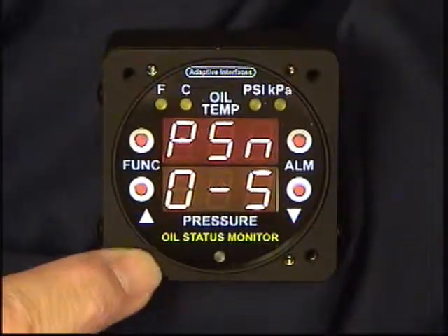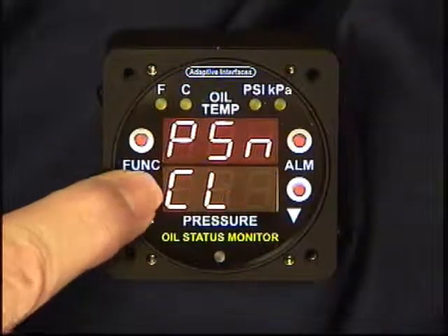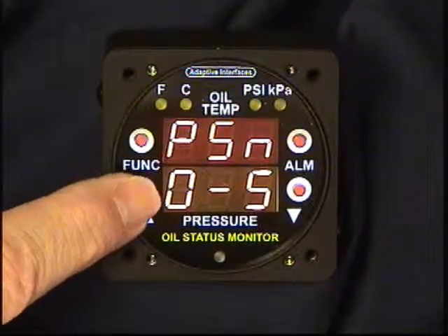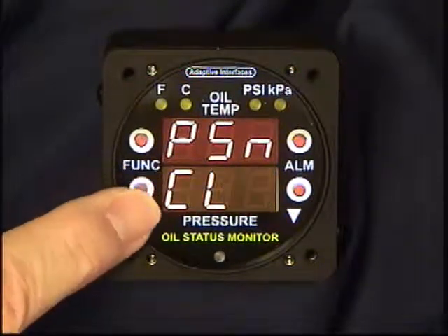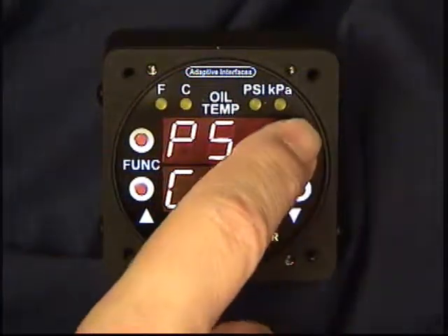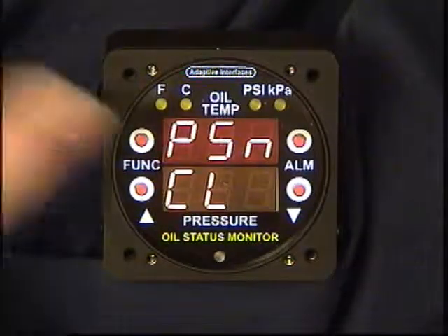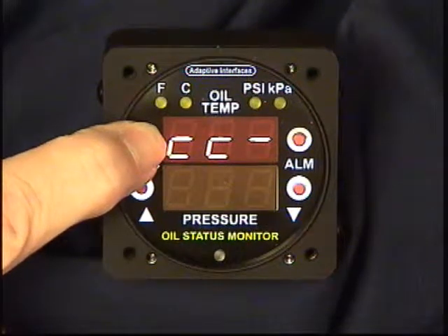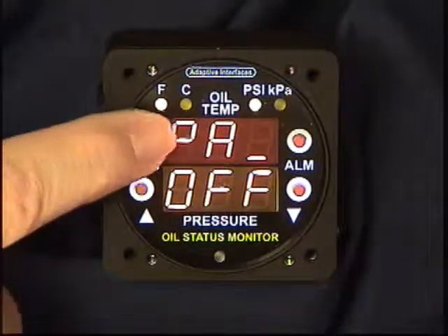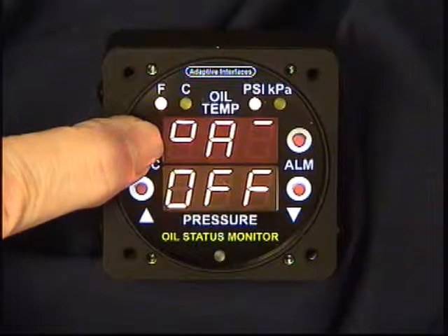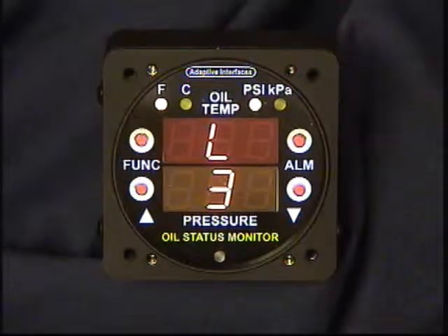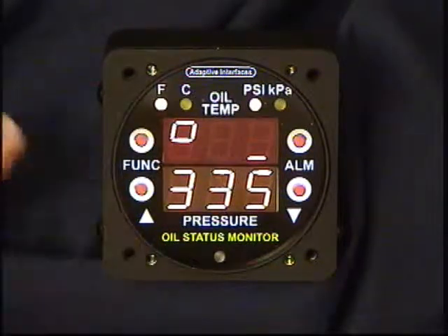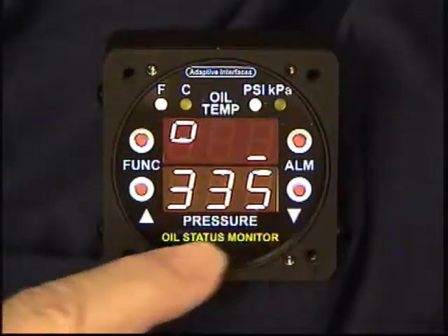And the pressure sensor, the options are again a current loop sensor, a resistive sensor, and a 0 to 5 volt output electronic sensor. And let's go ahead and set it for current loop and see what our options are now. We'll go back up to the calibration values by holding the button in. First we've got to go to alarm levels, and then we can go up to the calibration data point values on menu 3. And now our options for a temperature sensor are always going to be LM335.